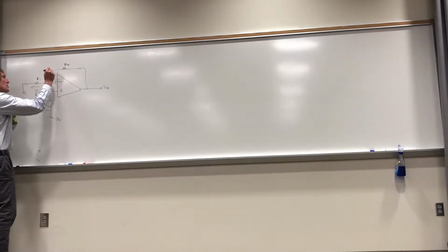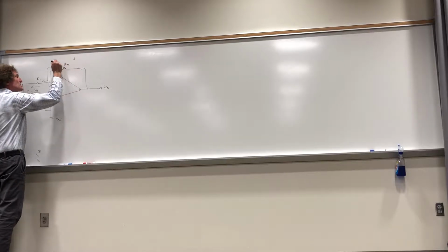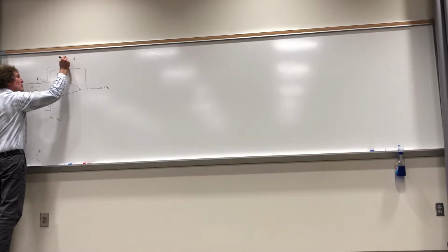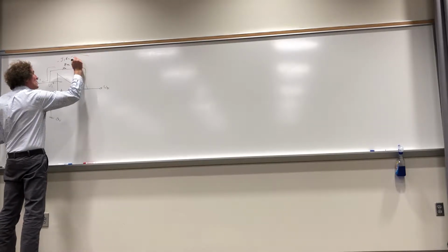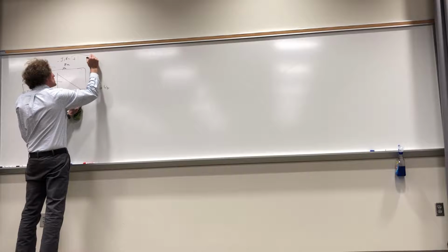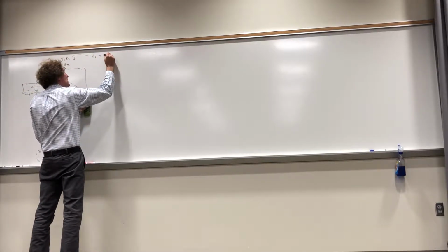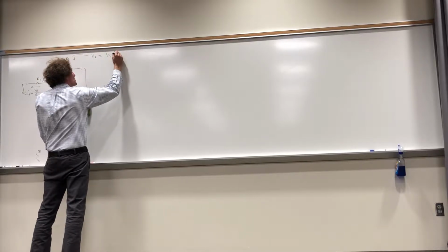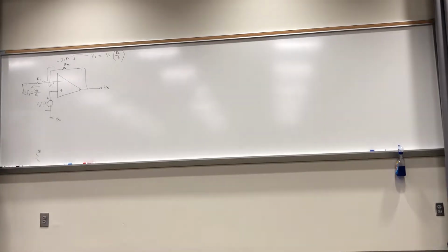Now that means all the current is coming this way, right? If I just call this I1, I know that this voltage is simply I1 R2, right? Or I can say that this voltage right here, call it V2, is equal to V in times R2 over R1. Do you agree with that? I'm calling it V2 there. Y'all follow me? Show of hands here.